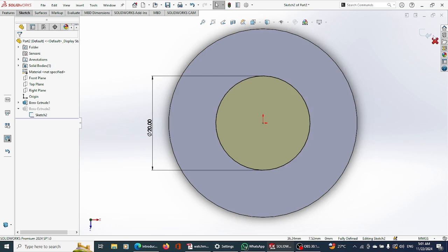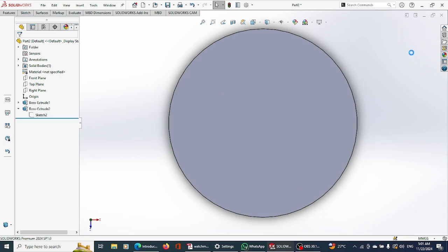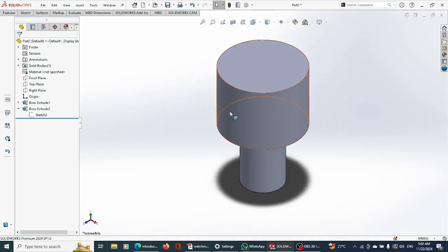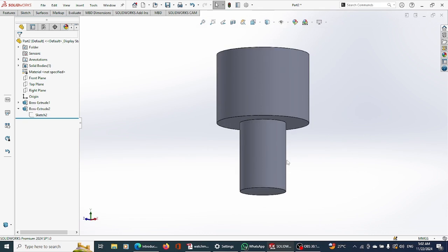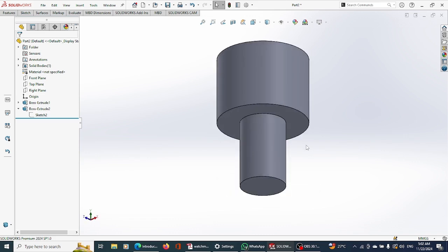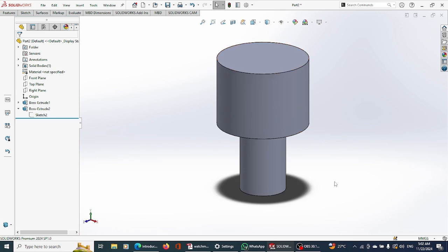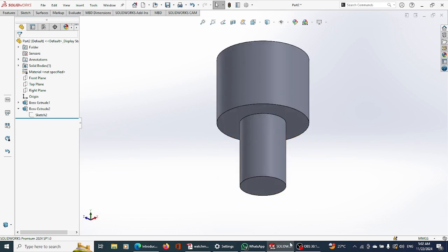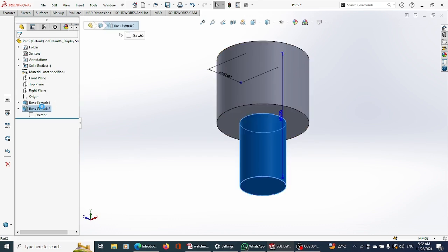See what I mean? Ctrl 7. I hit Ctrl 7 to get back to this form. Now I told you before, I don't want this guy to be extruding 60 from here. What if I could just decide to draw the sketch here on this face instead of on this face, so that I just extrude 30 downward? See what I mean? I delete this guy.